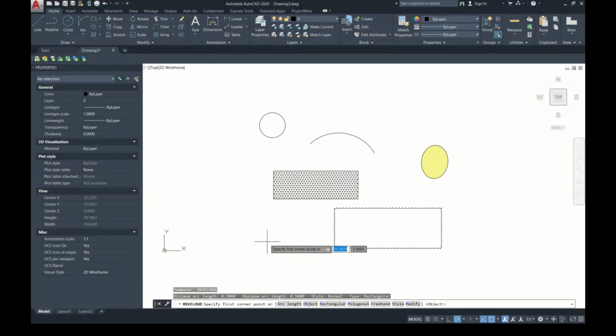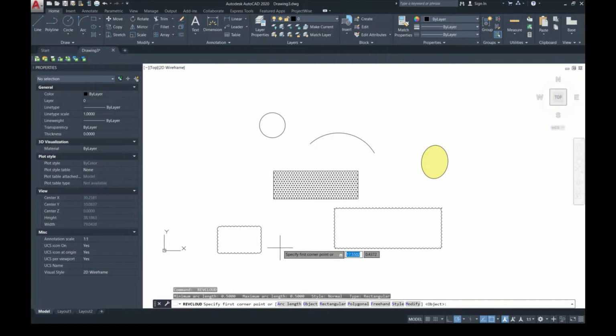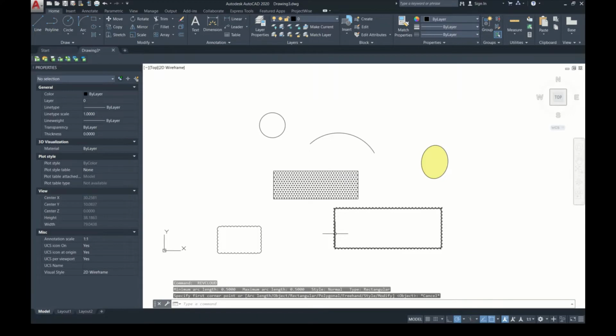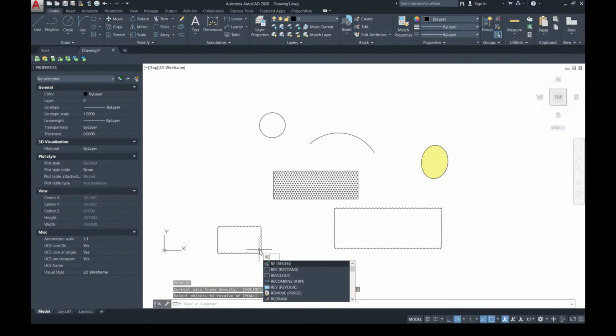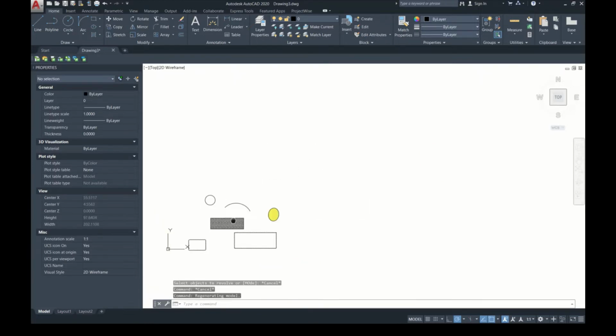So again I switched on this command and giving rectangular, polygonal, freehand, everything we can use. So RVC is the command. Revision cloud, it is RVC. Okay.